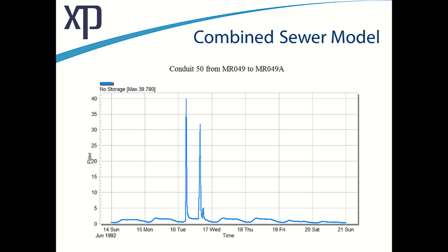And that's why many modelers won't even include, or will include a constant flow down at the bottom here for the dry weather flow, because it's such a small impact that is it really necessary to develop all those flows. That's something that you will have to decide on your own as an engineer. Is it important to show the pattern and show that that's in there, or a straight line, or not anything at all? So I'll leave that to you to decide.